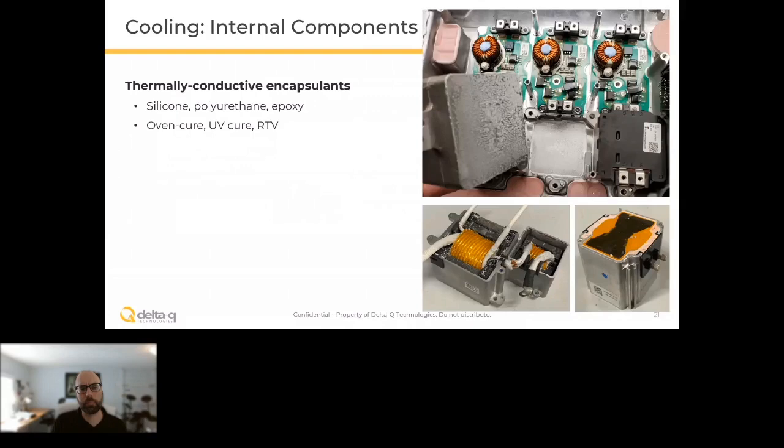And in all of these, you've got transformers and inductors that have been dropped into extruded or cast aluminum boxes, and then, with a few millimeters of gap, which is then filled with a thermally conductive silicone potting material, which does the electrical insulation, thermal conduction, and it can also act as a shock absorber for shock and vibe.